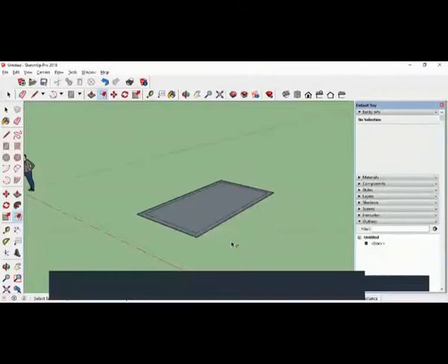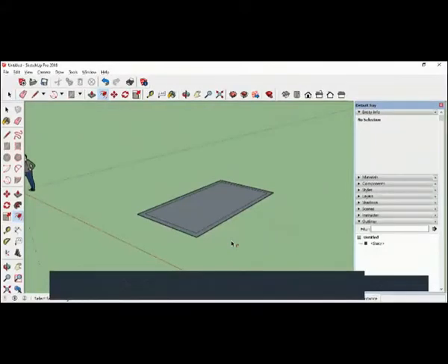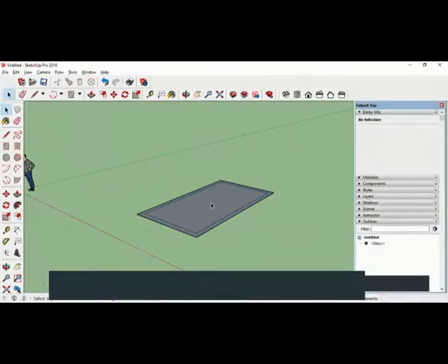So where is this offset command used? This is a very, very powerful command. We can use this in many places. For example, let me take a copy of this. How will I take the copy? I will select this. I can show a window like this, or I can click 3 times continuously.